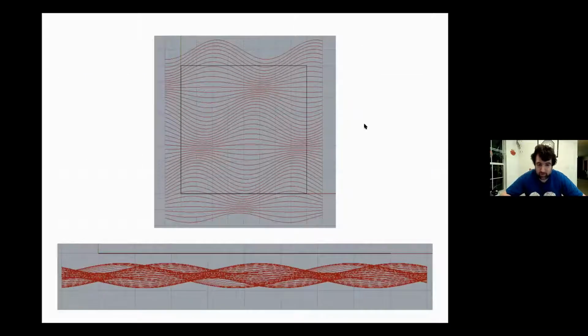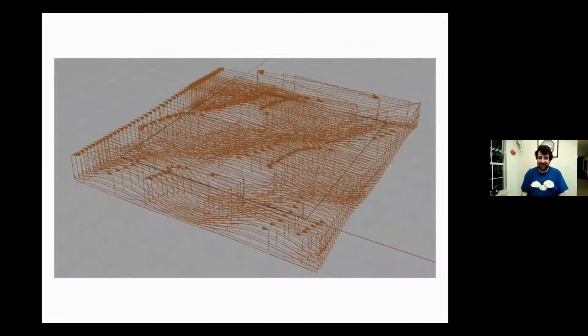And here is a couple more views of the curves. And now this is what the software comes up with. So one thing that you need to think about when pushing a bit into wood, and you saw that in the first video, is that you can't just push the largest bit deep into the wood and start moving horizontally. That's going to cause a lot of problems.